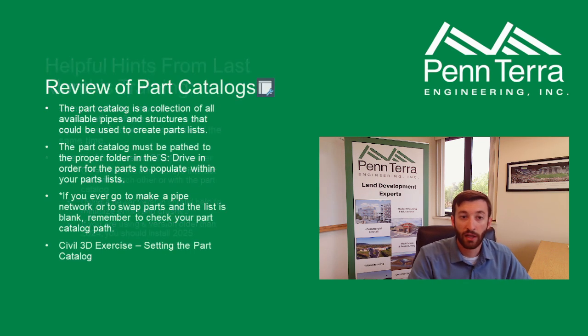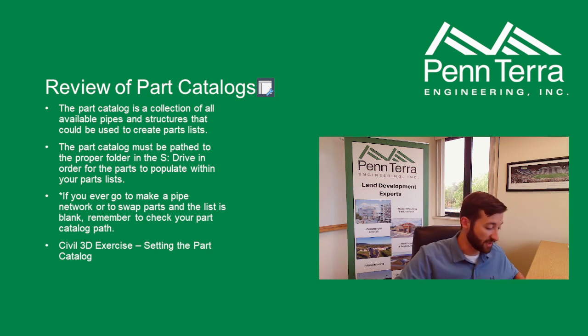So to get started, we're going to review parts catalogs. So this is essentially a listing of all parts that we have access to add to our parts lists. We keep them on the S drive. If you ever go to make a new pipe network or swap parts or something like that and the list looks like it's blank, make sure the catalog is pathed. So I'm going to show you how to do that. We're going to jump into Civil 3D.